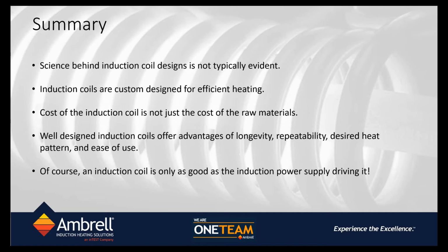So to determine the optimal pitch, we will actually start the induction heat, observe the pattern of the heat it produced, and then where you have the requirement to have higher heat, you would then turn the induction heating power off and then tighten the pitch. And this is basically an iterative process that has to go back and forth between heat cycles to be able to determine what the optimal pitch is of that induction heating coil turn.